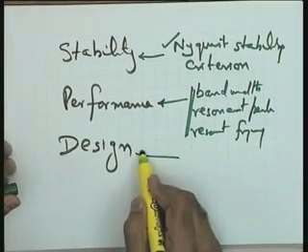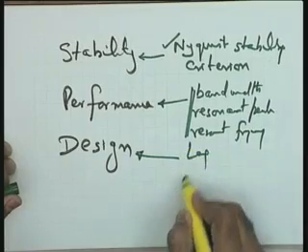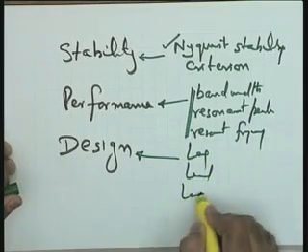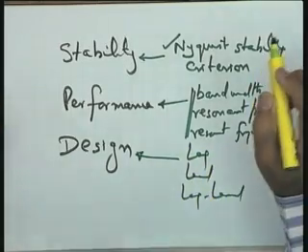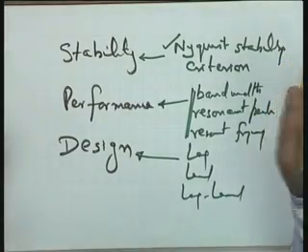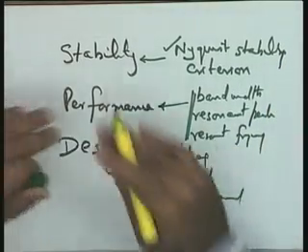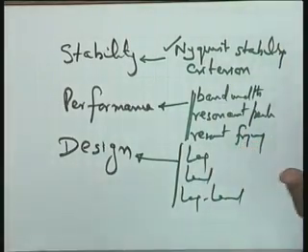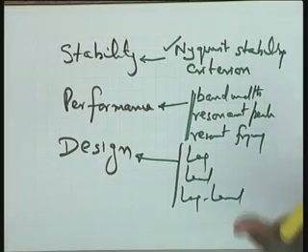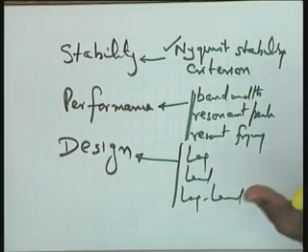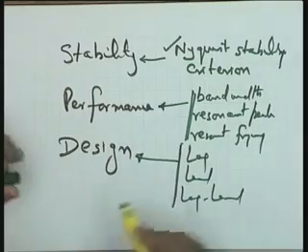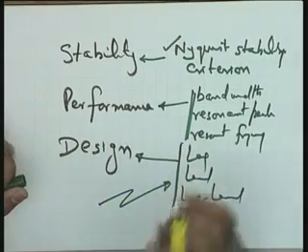The design, yes, we had the lag compensator, the lead compensator, the lag-lead compensator in the time domain or with the root locus method. You will find that all these basic compensators, for which the op-amp circuit has been given to you, work satisfactorily when we go to the frequency domain design also, and the design method becomes easier.